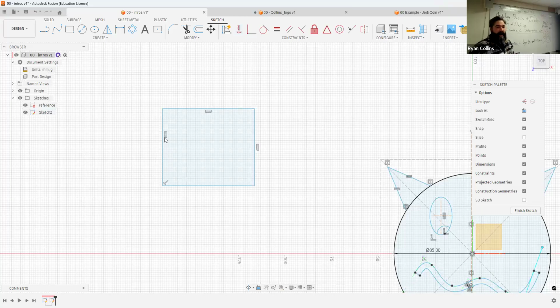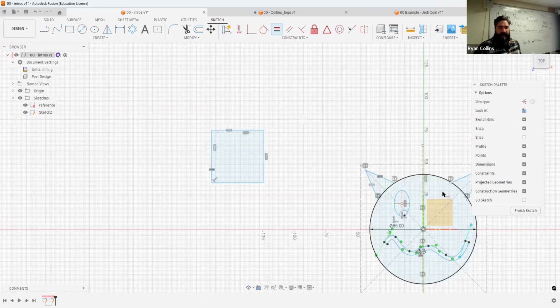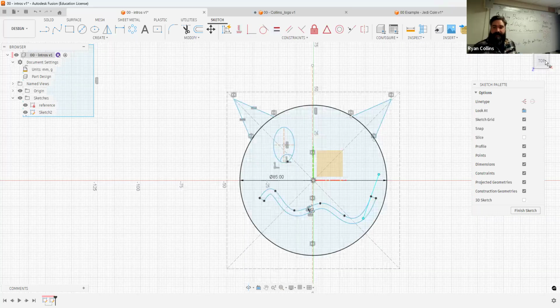Same thing goes, all right, I want these to match. Well, I'll go back and use that equal tool. I'll use this as my reference. And now if I select the top, it's going to snap to be equal to the sides. So now it just made a box. Hooray. I made a pretty janky one to begin with, and using constraints, I snapped it back into dimensional work. So just a way to work. Anyway, back to our nightmare cat.